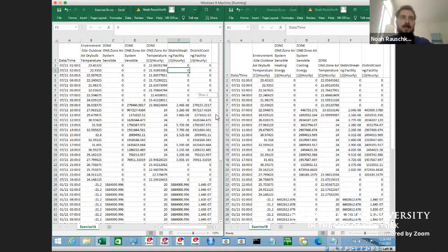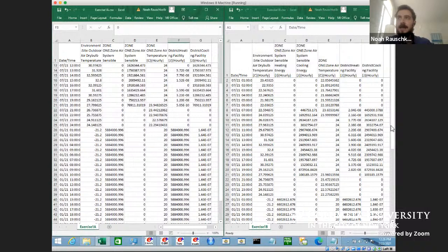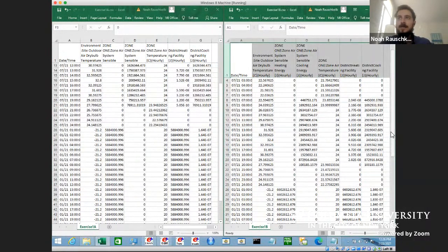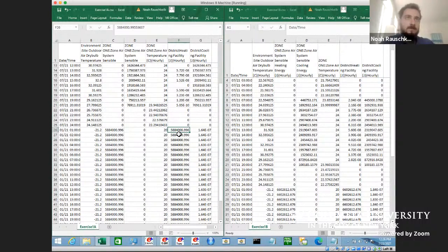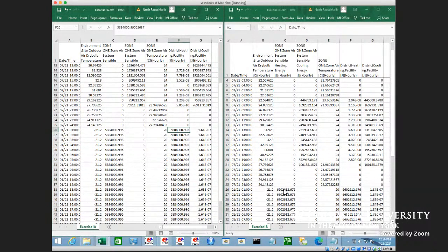And if you look down at the heating calculation, you can see that adding even the nice double glazed window increased our steady state heating load in the winter design day, January 21st, from 5.8 megajoules per hour to 6.6 megajoules per hour. So roughly 15%. That is the heat going into the building to make up for heat loss through the walls and surfaces.